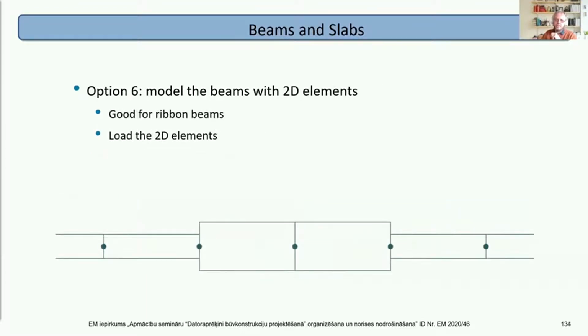And another option, you're modeling ribbon beams. You've got very wide, shallow beams on the column lines. For those, I would just model everything in 2D elements. The width of the beam is considerably more than the thickness, so 2D elements are appropriate. Now, you'll note in this, everything's on the centroid. I've not modeled either of them offset.